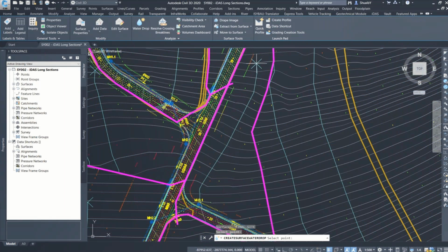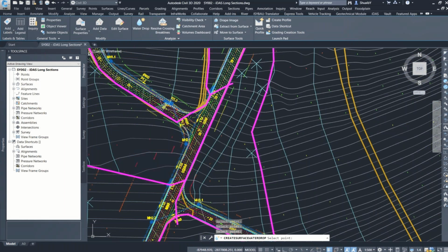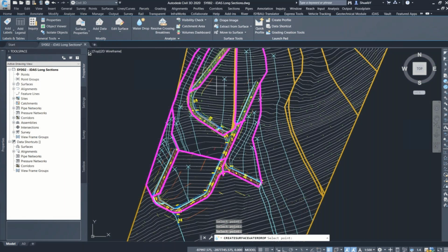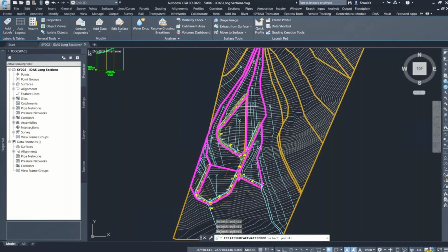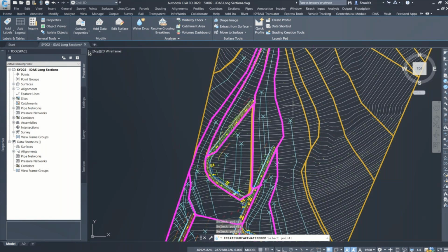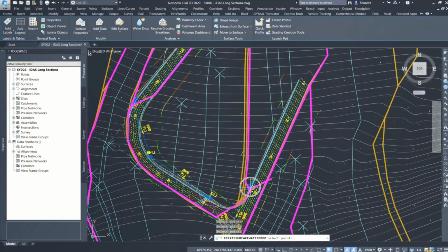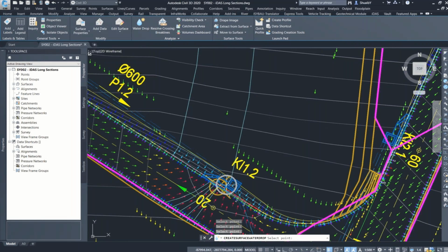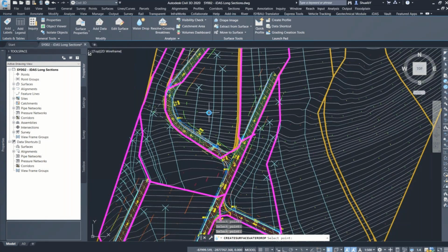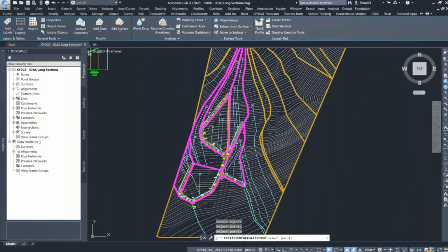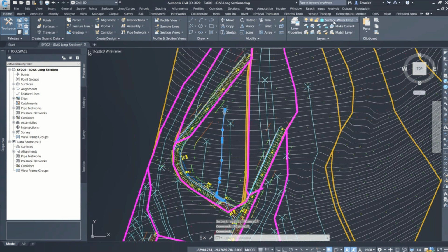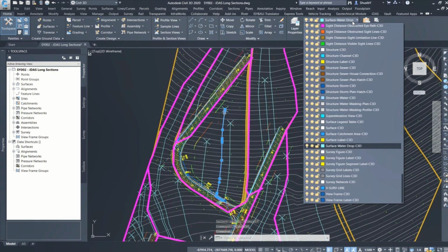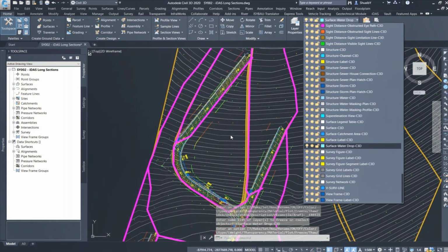I'll give you an example for this catchment. Let's check the water part. So again, water drop analysis. Can you see it's linking perfectly to my curb and channel configuration on my road, and it's going to be draining to my catchment at the bottom. Again, I can click more and more of them just to give you an example, but you can see this helps you a ton when you're trying to size it. There's another low point, and my curb inlet is actually positioned correctly, and it means my road design is on point. So again, roads and stormwater, if you're both on this, well, I can see a lot of you are, please work together to get a good optimized design. It's very important, right? So again, these are the water drop analysis.